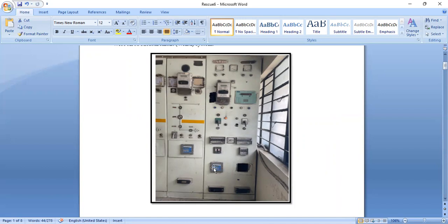Differential protection is related to the current magnitude. This type of relay we can also connect with this 22 kV control panel, called Rohit Tantra in Marathi. That means it is called the control panel for the transformer. This is for transformer 1, this is for transformer 2. You can see here, this is for the cos phi, the power factor. These are the analog meters we can connect here, and there are circuit breaker alarms also. It will trip when a fault occurs in the system. It will show like that.